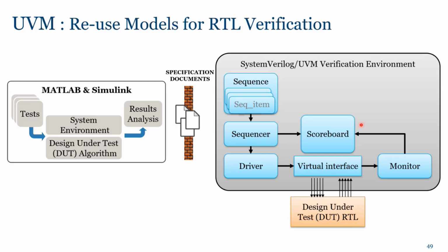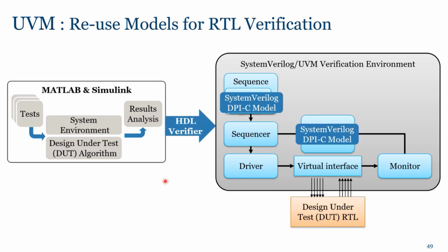You can use what you did in MATLAB and Simulink as the test, the system environment, the results analysis, and of course your design under test algorithm, in order to create the UVM verification environment, right? So you'll have your sequencer, your driver, your virtual interface and monitor, and you can even add a predictor if you have provided that in MATLAB and Simulink.